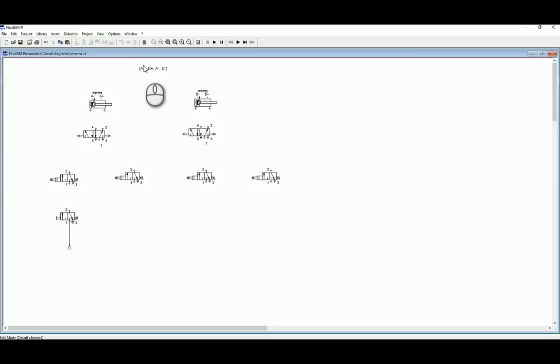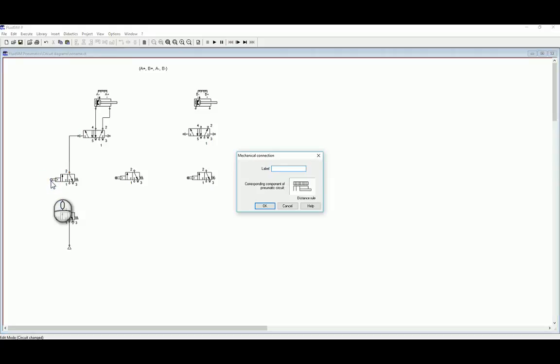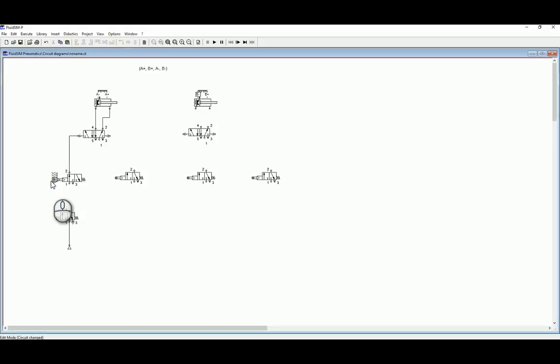So the first thing that should happen is A should go plus. So to make A go plus, we need to obviously activate port 4 from this 5-2 valve, which would make A extend. That means we need to activate port 1-4 here via the 3-2 roller switch, which should be then labelled B minus. And you see here, as soon as I label it, it shows the activated position because B is currently in its minus position. And I can activate that like so.